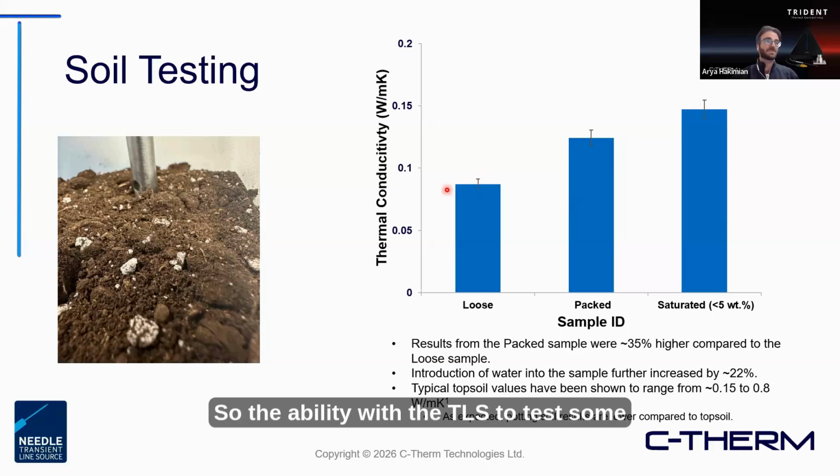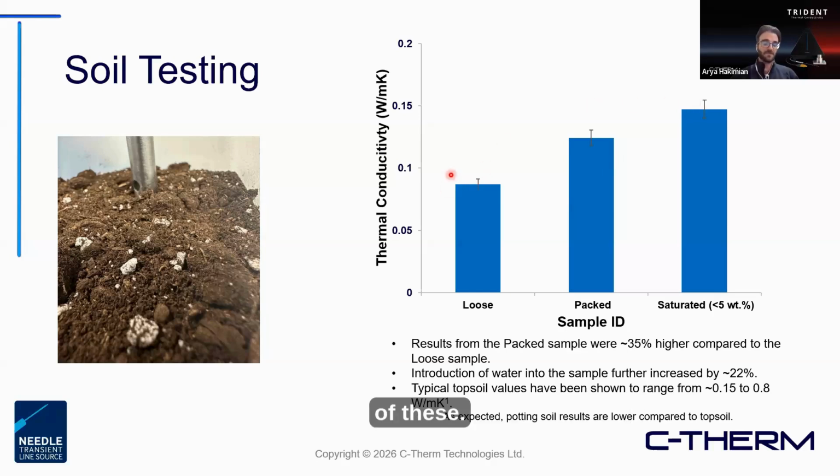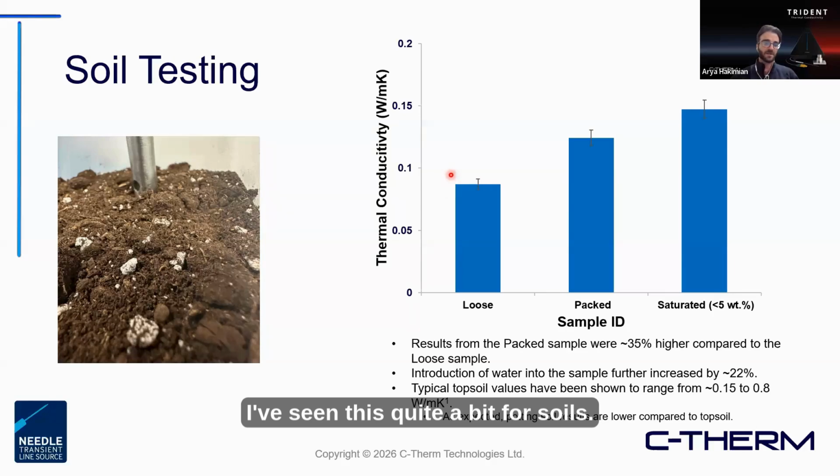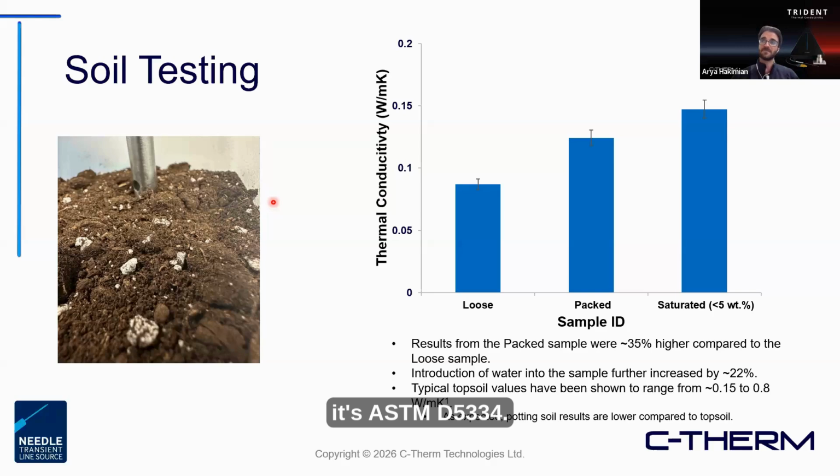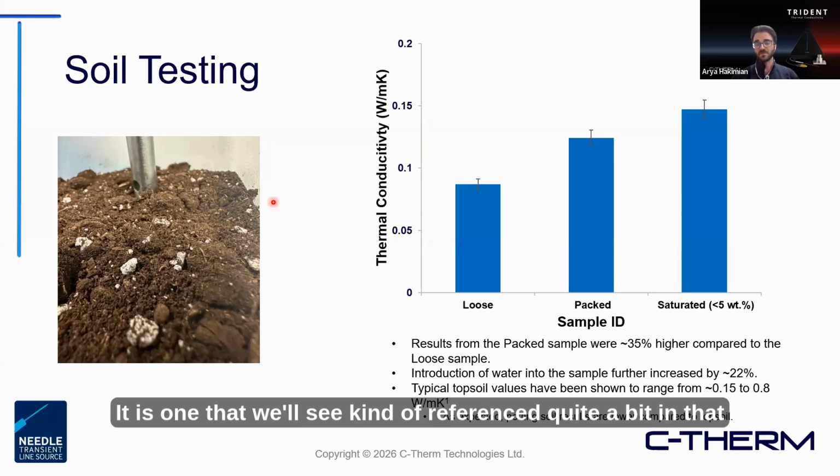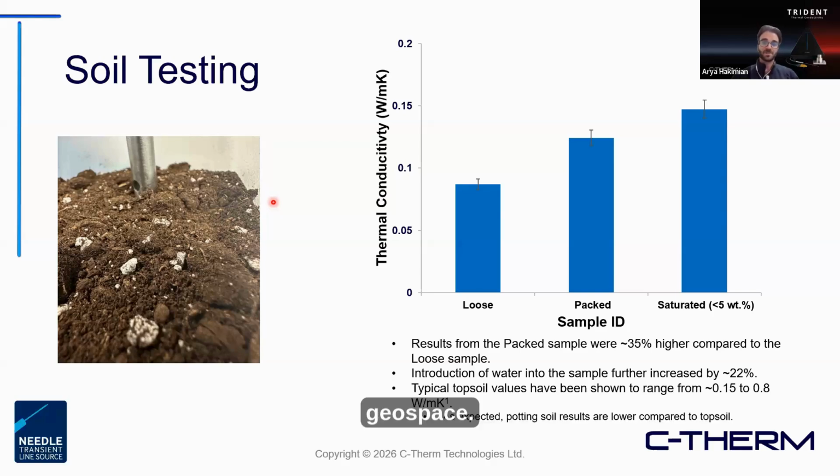So the ability with the TLS to test some of these, I've seen this quite a bit for soils, but also soft rocks, core samples, aggregate chunks, a nice potential pathway there. And again, for geological testing, it's ASTM D5334. It is one that we'll see referenced quite a bit in that geo space.